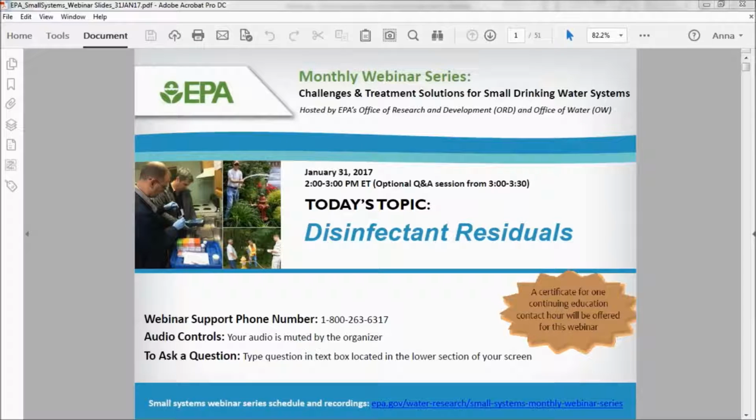If you wait too long in a free chlorine test, the chloramines will start to bleed into that test. And quite honestly, if you have a chloramine system and you can measure that you have measurable free ammonia, you really don't have free chlorine, because free chlorine is going to react with the free ammonia. So yes, when you have a chloramine system, if you're measuring free chlorine, you can have some positive interferences.